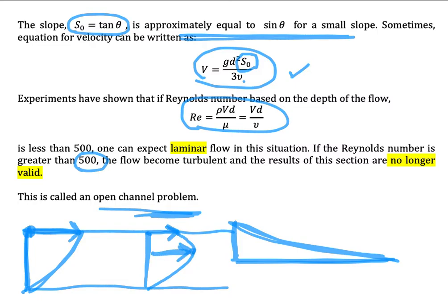If you study the open channel in real, not in small scale, it will give us a turbulent open channel. So the maximum velocity will occur at a location almost 1/3 from the top surface. That means if you see a river and so on, the maximum velocity of a river is not on the surface but at one third of the depth from the surface.